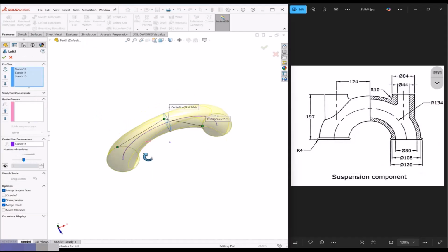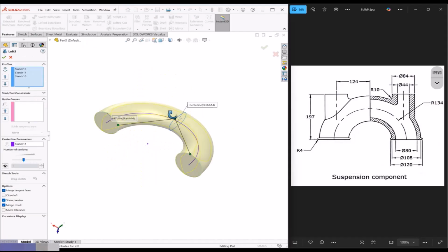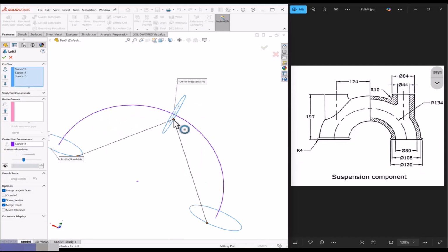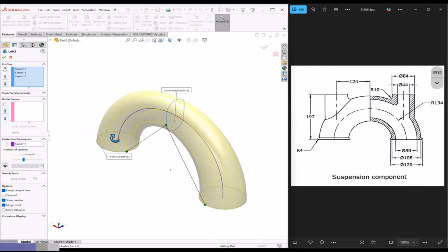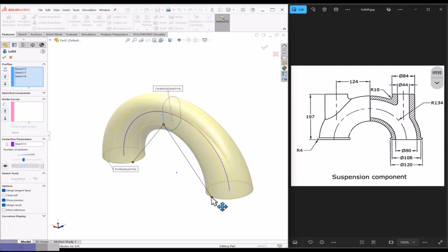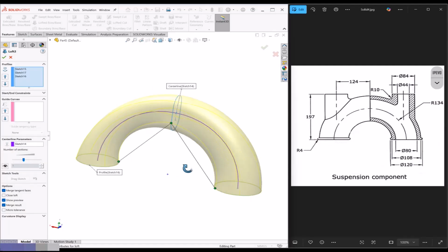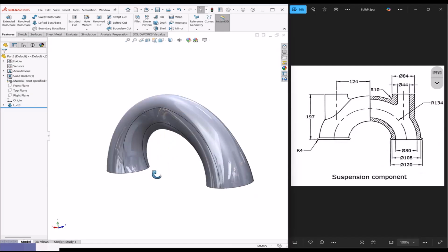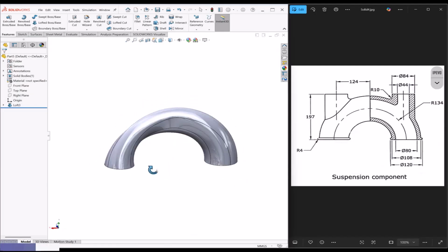How you can correct that? By moving the pointer exactly by aligning to each other. You just move them. So you have to see where it can give you the outcome, and arrange it in a better way. So like here, you can see, I think twisting is removed, or you can move this also, see, and move this and check now. See, earlier it was showing some twisting here. Now it is corrected. Okay.